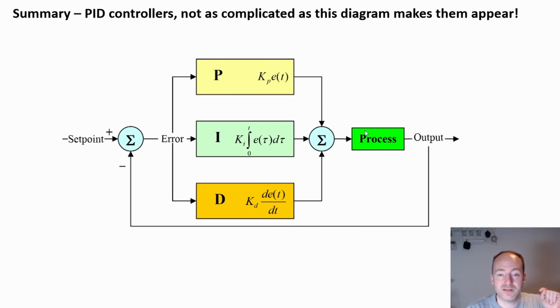So in the example, that was the adjustment of the heating power to our heating element, be it the boiler or the little heating mat I have in front of me now. That changes the temperature and the process repeats. And that's a PID controller. You can use this for basically controlling most systems. All you need to do is tune the Kp, Ki and Kd appropriately, and you can always get that critically damped response.